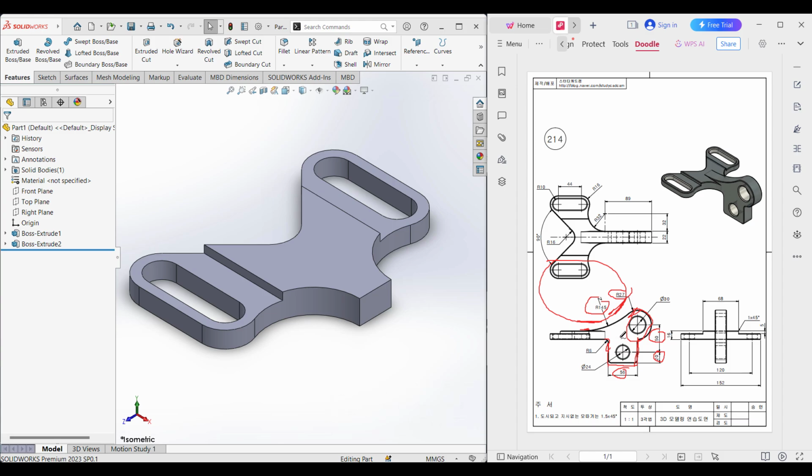Then I'll close the shape, then I'll extrude boss it to 22 unit. And before doing that I have two extrude cut circles, one is 30 unit diameter and another extrude cut circle of 24 unit diameter, which has a distance of 20 from the vertical line and at the middle point.